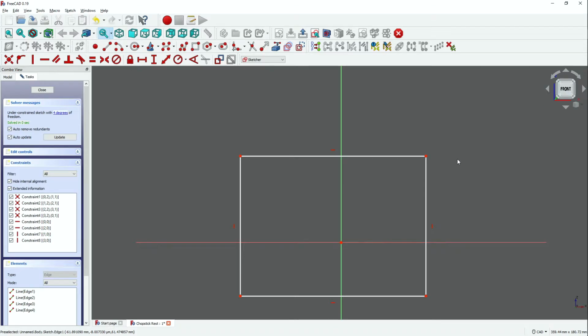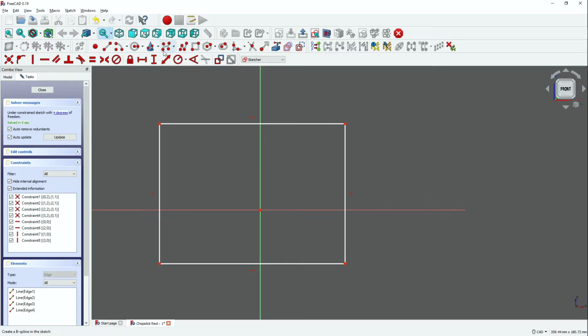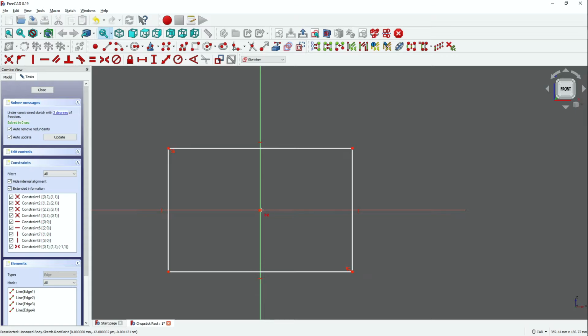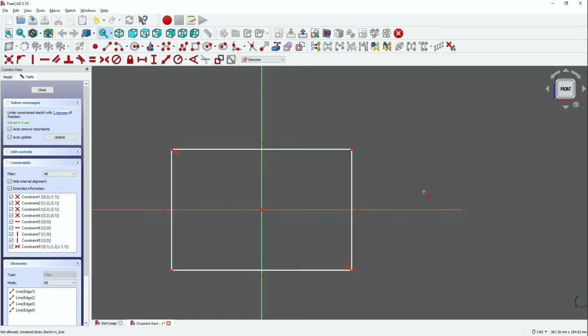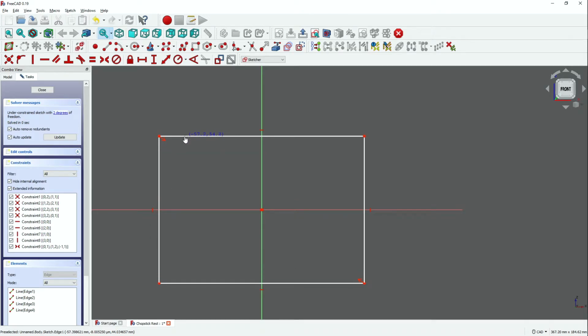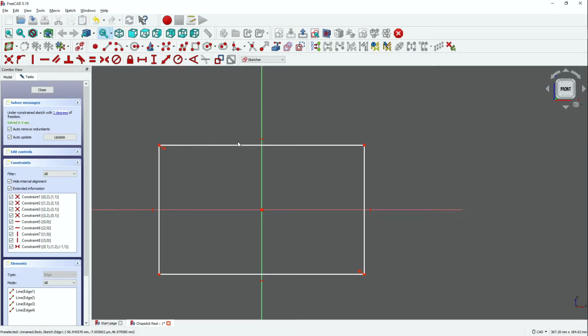Free software. All right, so if you go to the symmetry tool, you click on this point here, click on that point there, and then click on the point you want it to be centered on, and there you go. Now, it should give you the exact same result that it's constrained to there. So the center of this rectangle is at this point I dictated, which is the origin in this case.